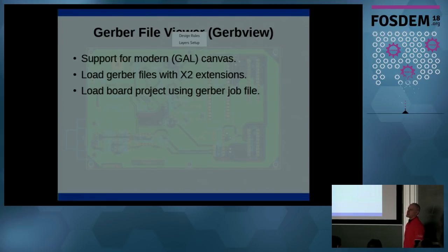Well, right now it's 32 and 32. 32 copper and 32 others, but some of the others are defined, like the solder mask and the silkscreen layers are predefined. Sure. I mean, do you need more than 32 copper layers? I had 48 planes. 48 planes? Okay. We've talked about just making it infinite and editable, but right now it's limited to 32 and 32.